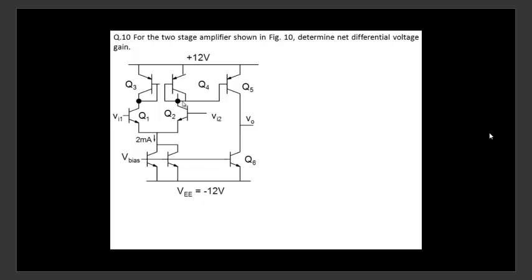Saturation where? Q3 and Q4 are this thing, right? Q3 and Q4 are with base and collector, they will always be in active mode. If I have 12 volt here, then the drop from here to here would be 0.7. So I have 11.3 here and 11.3 here. But what you guys can see is 11.3 here and 12 here. So there's also 0.7, so there's no problem with biasing or anything.